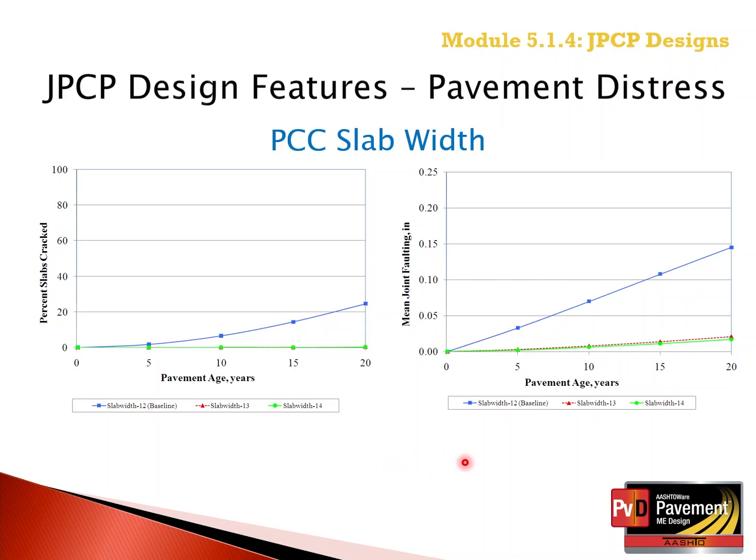A cautionary note regarding slab width. Using widened slabs increases the probability of longitudinal cracking in the slab. The software was not individually calibrated to longitudinal cracks simply because of using widened slabs. It is recommended that the designer limit the width of widened slabs to 14 feet.